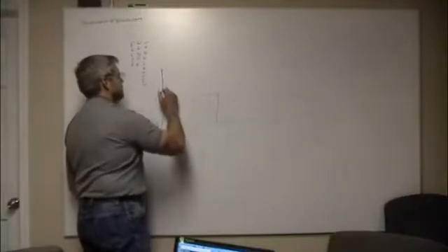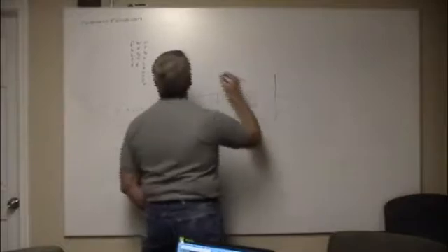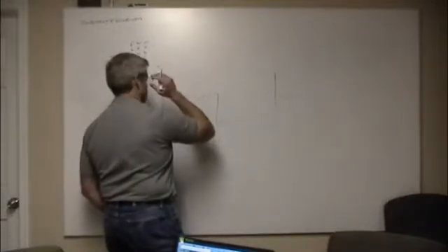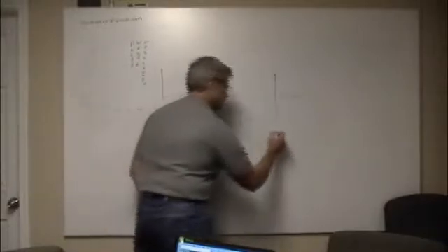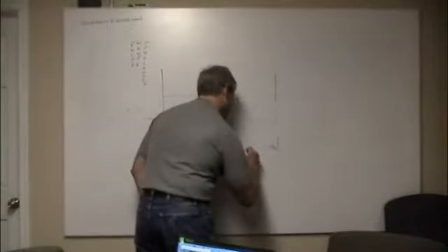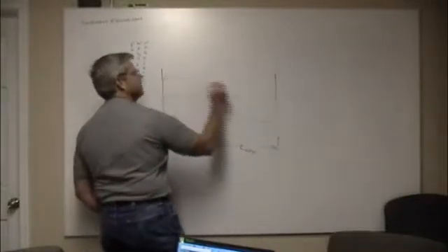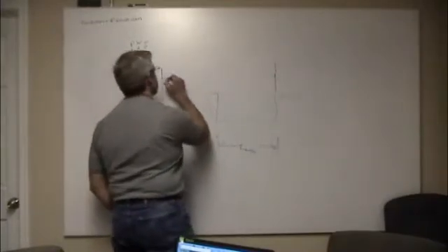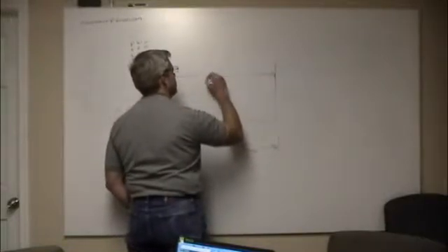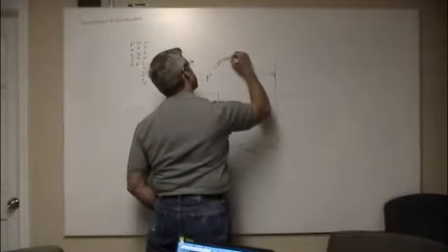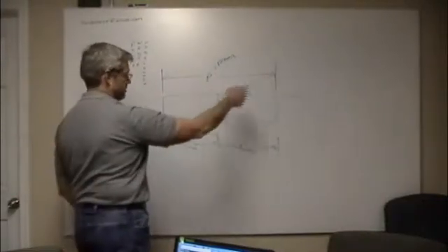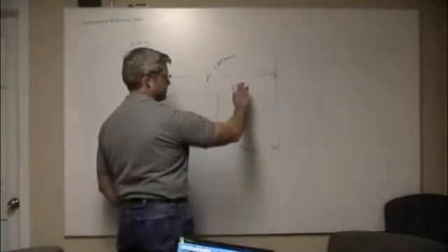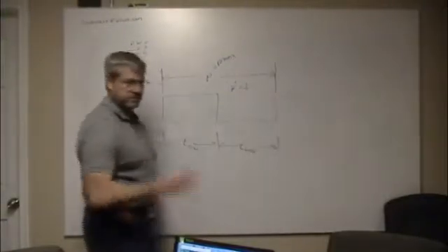So if I have a signal that's doing this, on, off, there are some things we talk about here. We have time on, we have time off, and this total time is called P, that's your period, and 1 over P is equal to the frequency. 1 hertz, 1 over 1 is 1. It's 2 times per second, 1 over 0.5 seconds is equal to 2 hertz, and so on.